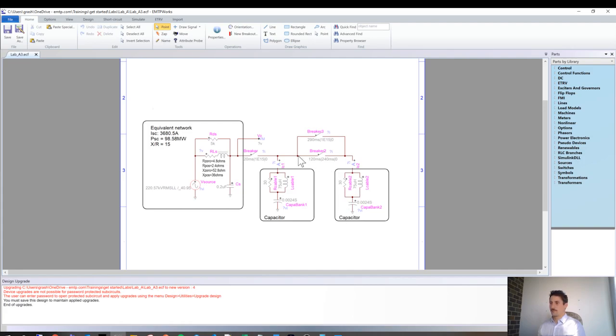You will have one circuit between those three capacitances, this one being very small, of course, so it will basically be between those two. So that's the effect of back-to-back switching. Between the two capacitances, we have only very small inductances compared to the rest of the grid. And so when we close that, those very small inductances will create very high transients in between.